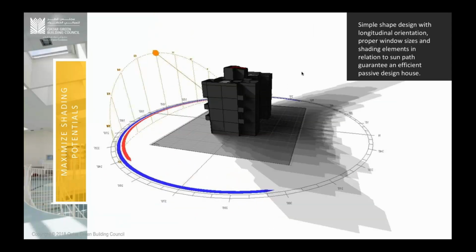Again, you can use and test all of these principles using energy simulation tools. Now even from SketchUp to Revit and others, you can turn on the solar path and experiment with different days, any hour or day per year based on your exact location, to see how the building will behave from a shade and shadow perspective.